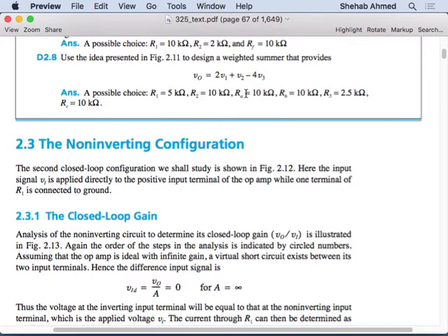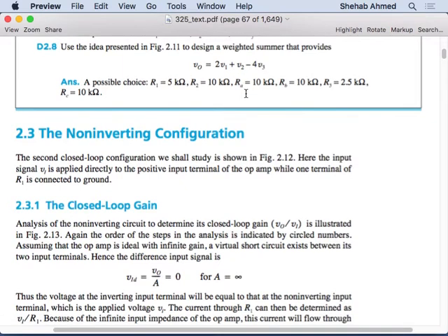We're going to discuss a difference amplifier, where I take the output from this one and the output from this one and subtract them from each other. We saw that subtracting is sometimes interesting when we have a common mode signal at the inputs of both devices. So we will look at a difference amplifier as well, and then some other details of op-amps. Anyway, non-inverting configuration.